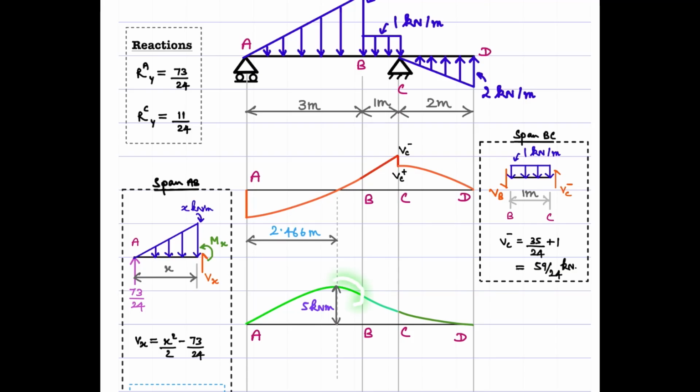Okay, that's how it is done. And then similarly, you need to determine this pattern here, which can be related to the corresponding ordinates of the shear force diagram. And when you come to this portion, you have a positive ordinate here. That means the pattern here should be such that you have slopes which are negative and then which should be increasing. Okay, so you can relate the slope of this portion to the corresponding ordinate here. Finally, this pattern should correspond to the positive ordinates here.